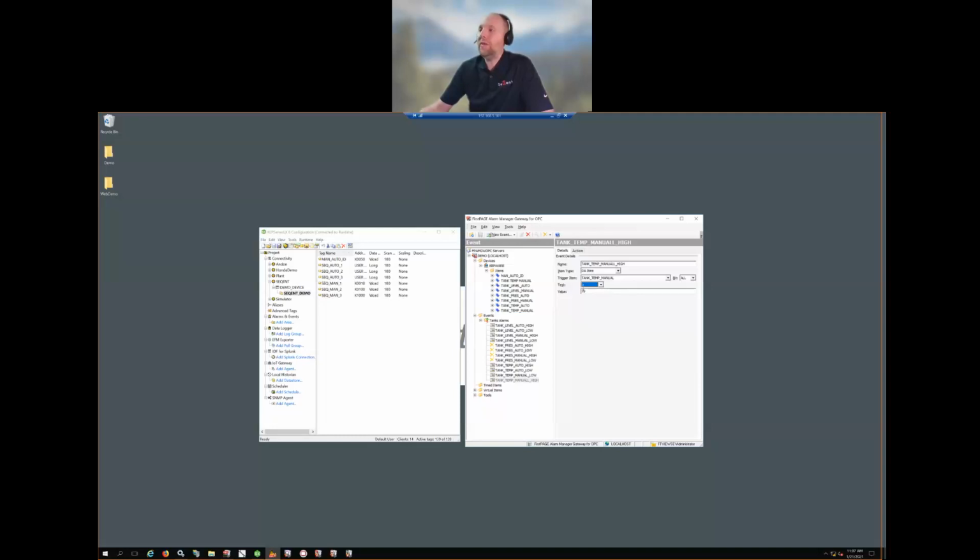In addition to that trigger configuration, we also have an action tab here, which is highly important. This allows us to take additional information from the OPC server and push it out to an end user when that alarm is triggered. So maybe it is a string related to a description of what that issue is. Maybe it is a SKU related to the specific piece of manufactured product that is occurring at that time.